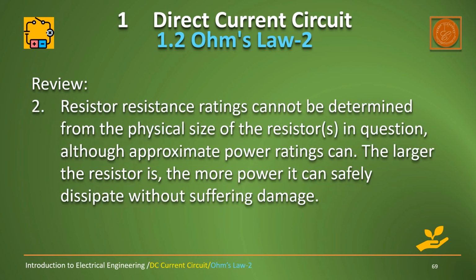Number 2. Resistance ratings cannot be determined from the physical size of the resistors in question, although approximate power rating can. The larger the resistor is, the more power it can safely dissipate without suffering damage.